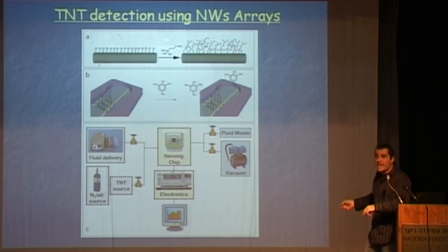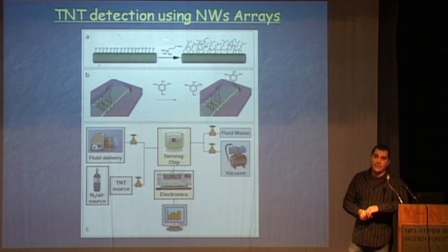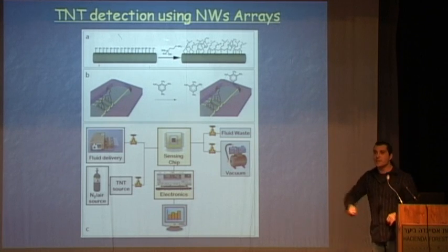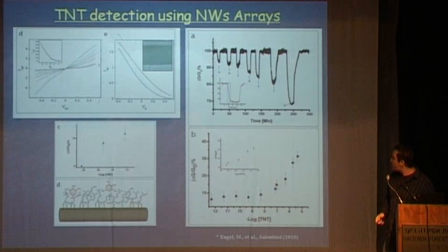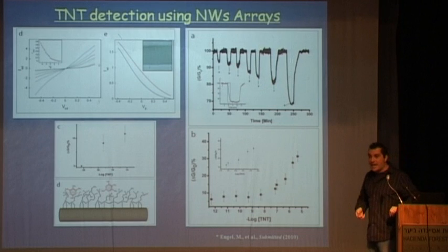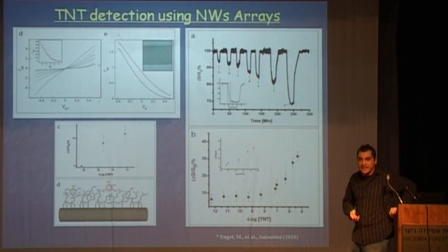So then we expect to be able to read with high sensitivity those negative charges that are created on the silicon nanowire devices upon the recognition of TNT. So this is the electrical characterization of the devices, and we can see here that interaction of the electrical devices with different concentrations of TNT leads to higher and higher signals. We have a clear concentration dependence of the sensing.